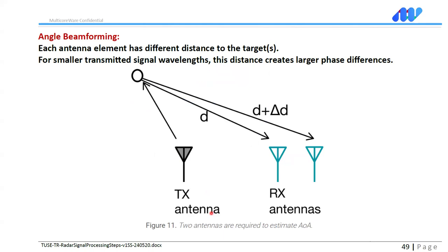So now we have the radar cube, ADC, pulses, and receiving channels. Those are fast time, pulses are slow time, channels are spatial, they're sampled exactly at the same instant. And then we calculate ranges, Dopplers, and finally here now, we're calculating the angles by taking FFT.